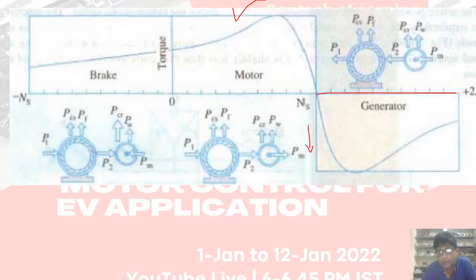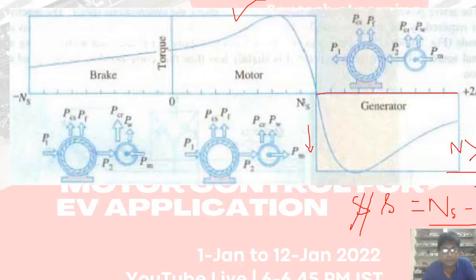But you have to operate the machine above the synchronous speed. Your slip is basically synchronous speed minus your operating speed, divided by synchronous speed. If your operating speed is greater than synchronous speed, that means the slip is negative. If your slip is negative, that means this n is higher than ns, then it will go to generating mode. And here this is the braking mode.